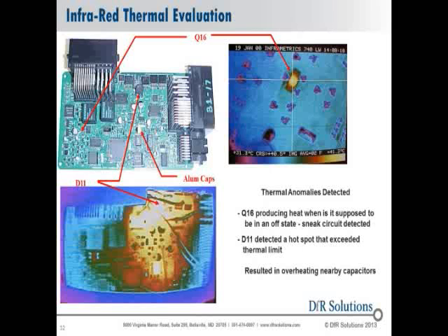we knew the caps were rated for the temperature of the application, but then we saw that the power distribution could raise the temperature of the local part of the board another 23 degrees. So we had to go in and increase the ratings on these capacitors to a higher temperature grade in order to endure this and get the same reliability expectations we want to get out of it.